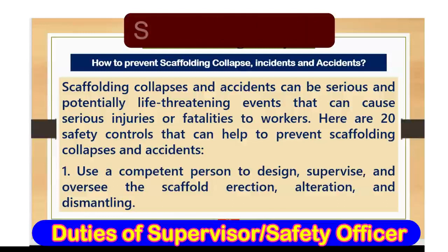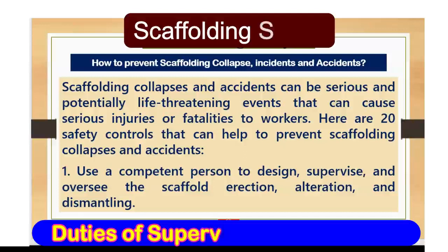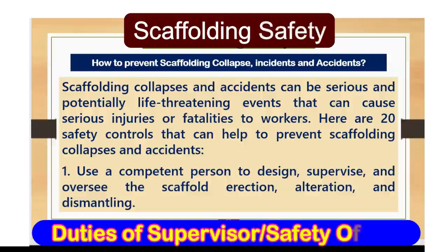Number one, use a competent person to design, supervise, and oversee the scaffolding erection, alteration, and dismantling. Key point, scaffold is a high risk activity, and it should be planned, designed, supervised, and overseen by a competent person. Competent person means a person with relevant qualifications, skills, experience, and motivation.